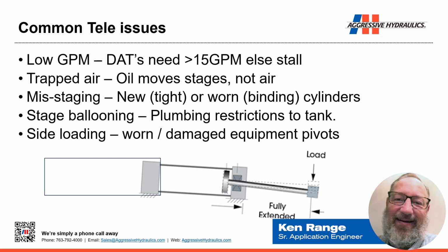The stage ballooning. This is a little bit of an interesting situation. We talked about how pressure applied to area creates force. And the larger the area that pressure is applied to, the greater the force that's created. Imagine a double-acting cylinder that's fully extended, and you want to cause that cylinder to retract. And let's say in this instance, there's an external force associated with retracting that cylinder, some kind of a weight of a dump body or a load or whatever it might be.